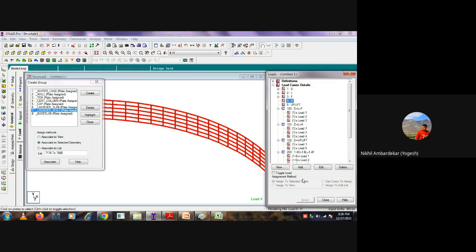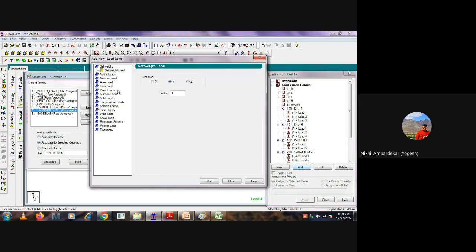Now next is soil load. Self weight of the soil on the toe. So that self weight is 20 into what is the height? 0.5, 4.1. Oh, sorry, 4.1 is 82 kilonewton.